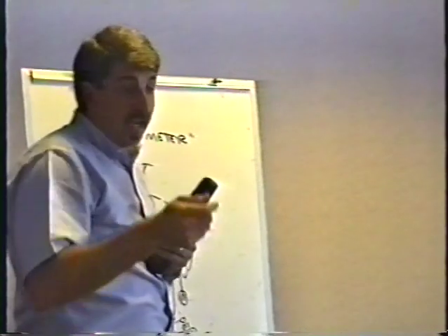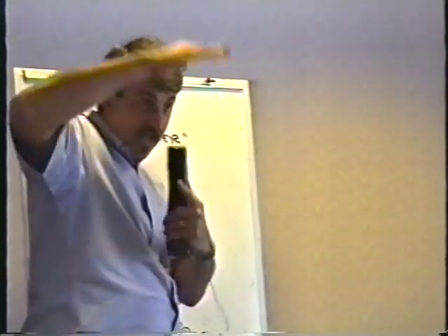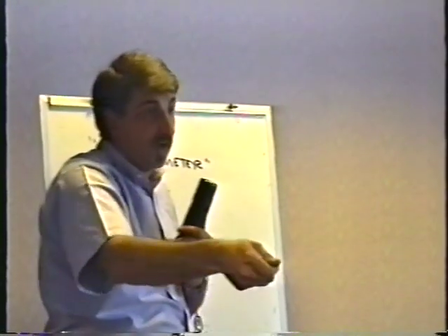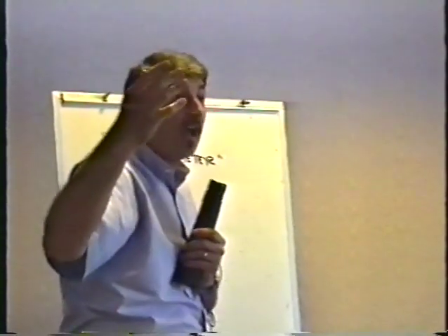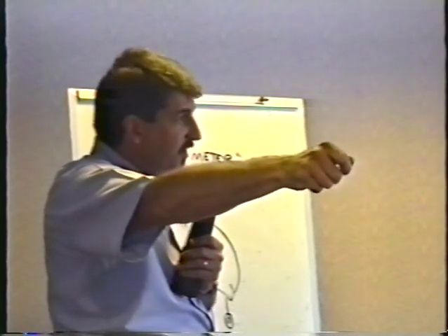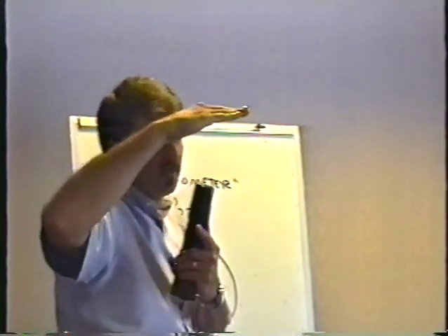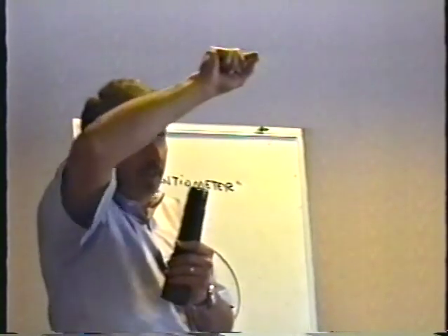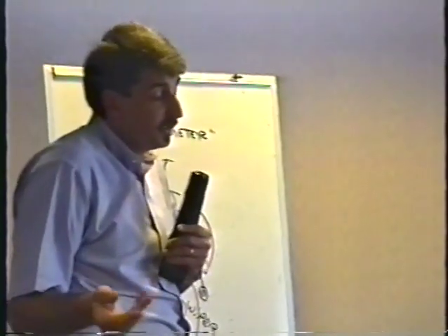I just took the vertical size pot and rotated it back and forth a few times, and the picture was solid as a rock. When I put it back, I didn't put it in the exact same position. I moved it over just a little bit, making the picture slightly small, which I don't mind, seeing a little black on the tops and the sides of the picture personally. And it was fine. That's what he should have done out in the field.